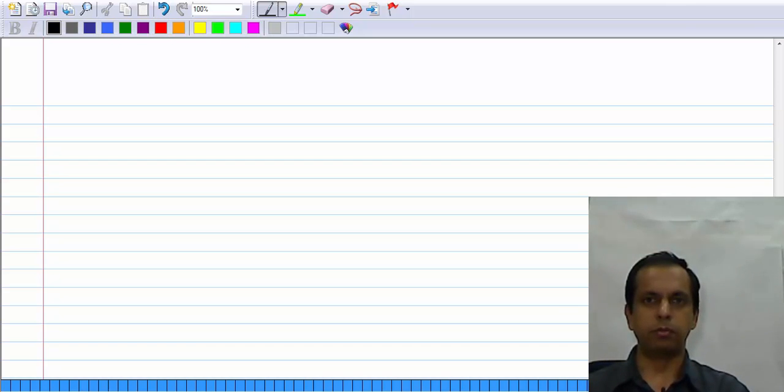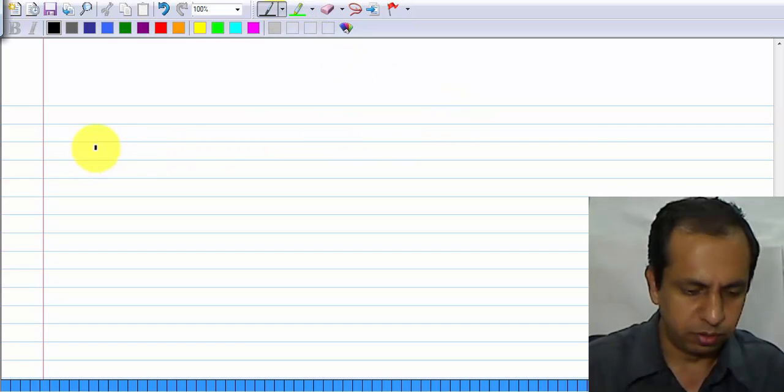We now have some form of an amplifier using a MOS transistor, which sets up the correct operating point as we want and also sets up the correct small signal incremental equivalent circuit, that is with the signal source connected to gate and source and the load resistance appearing across drain and source. The circuit we came up with was